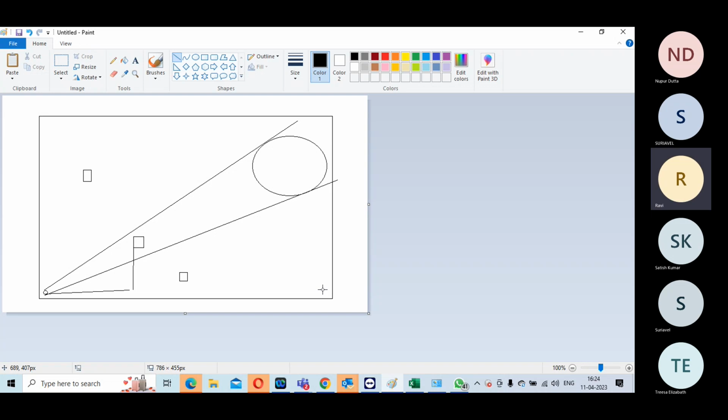After traditional CTS, you have to enable the timing modes and check the timing. Okay, the timing is really bad. Why? Somewhere the skew must have gone wrong. The cells have got displaced too much. So one of the things in post CTS you have to look at is the displacement. Even in placement, you have to check the average displacement and the max displacement.